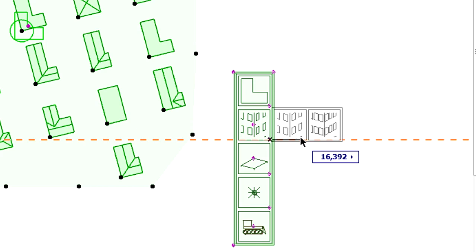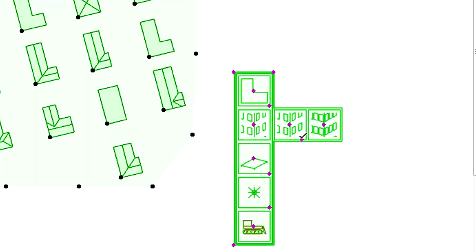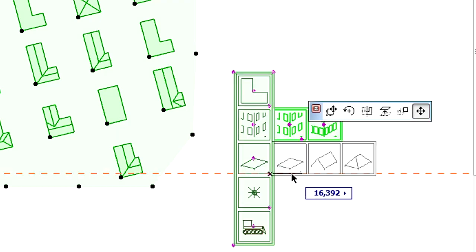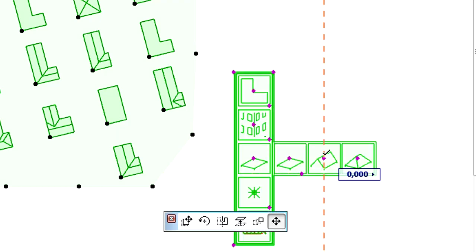The very same applies to elevation styles as well. We can select the desired new elevation style and then drag and drop this on the previously placed existing buildings to replace their elevation. The third icon allows us to modify the shape of the roofs.